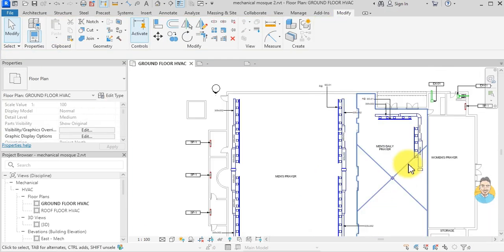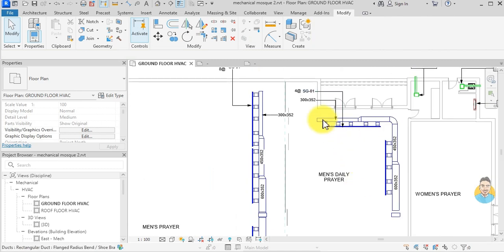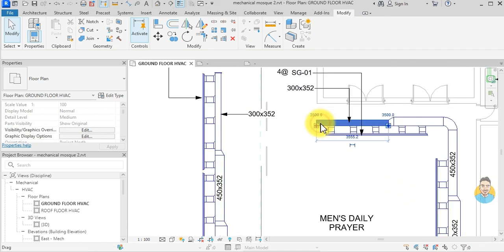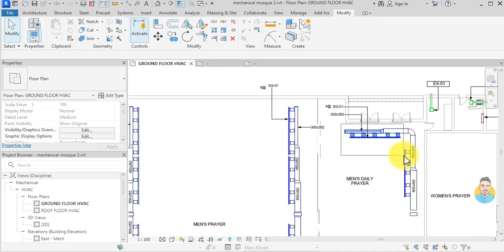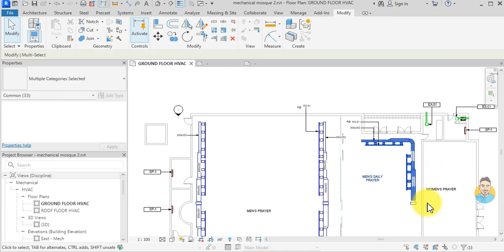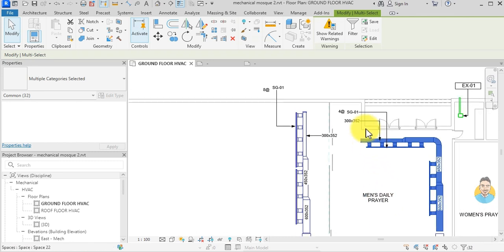Escape, and then I will do the same. I just mirror it before I connect it to this duct. I can cap open ends, and then I can mirror it. Select everything here. Shift to delete this selection. If I selected something by mistake, I can shift and subtract it from the selection. Control to add.